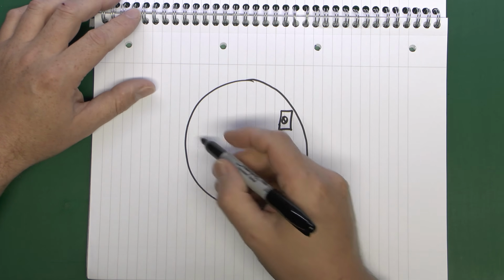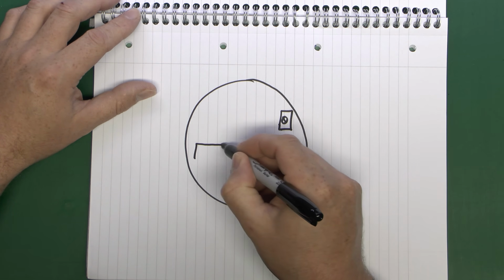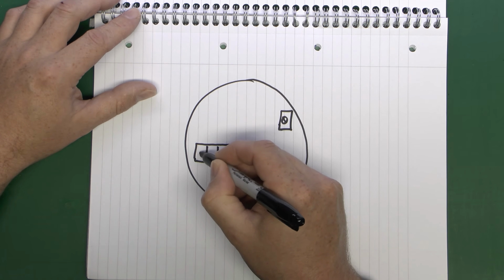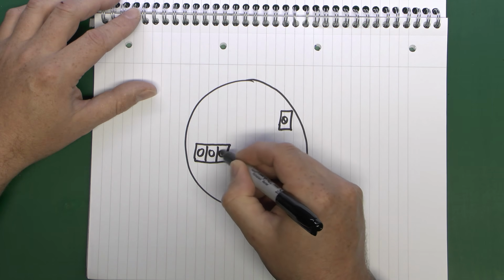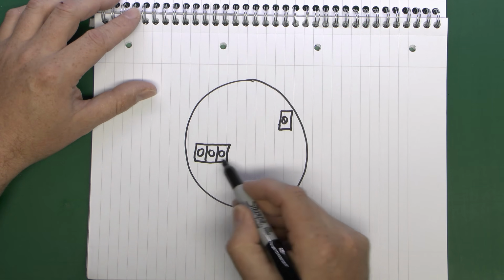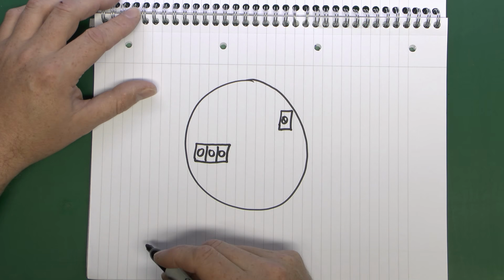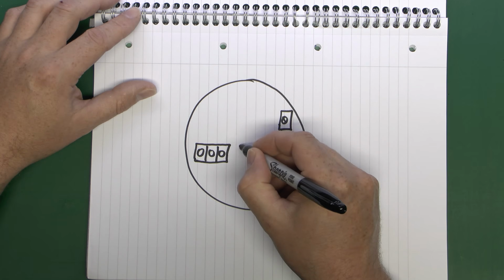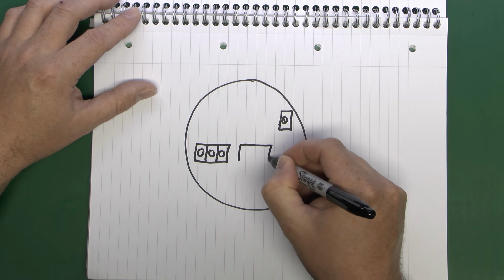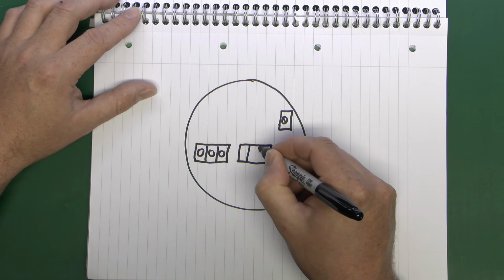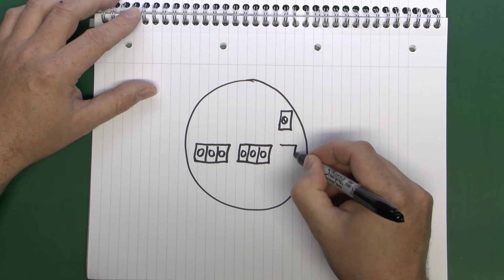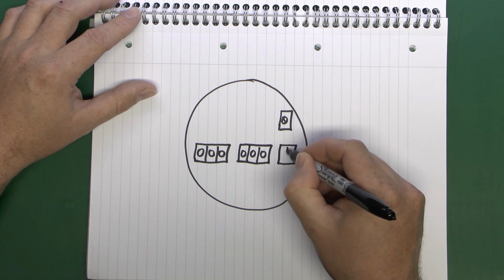And then across the centre here, they've generally got a section for the neutrals, and that will typically have 3 actual terminal holes in it. And all these are connected together. It's simply a block of brass with some screws fixed in, and that has, say, typically 3. We'll then have another one next to that. Again, that typically has 3 terminals as well. And then over the side here we'll have a 3rd terminal, and that typically only has 2 inside.